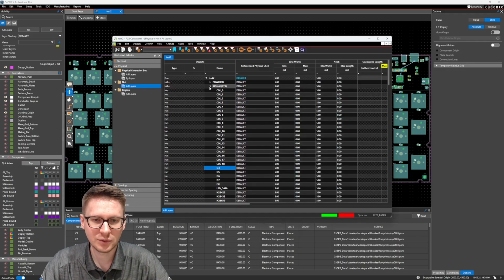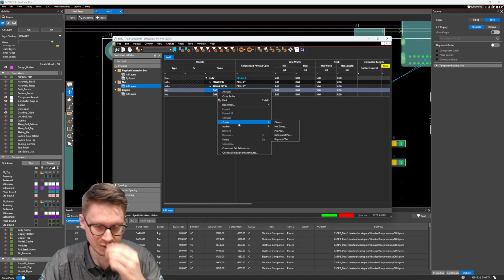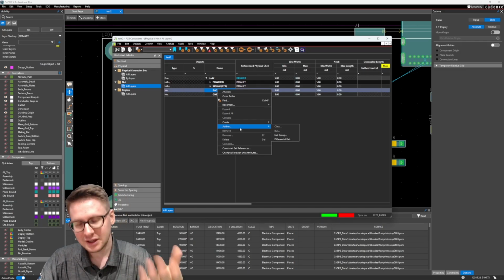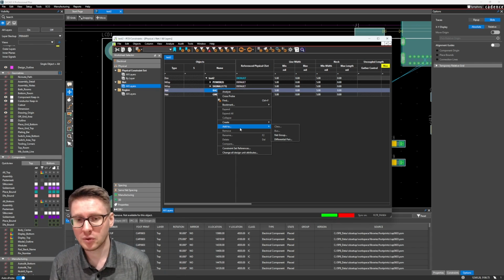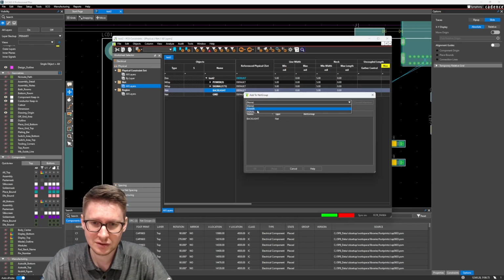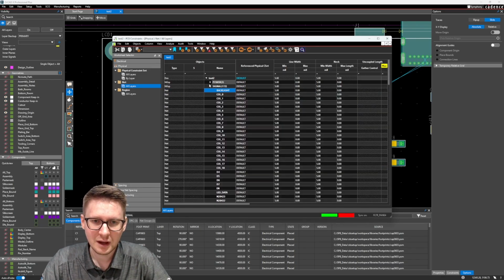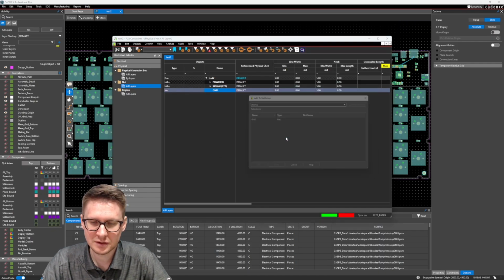And then finally, we have this backlight. I believe I wanted this to be also a signal net. Technically the backlight, if we were working with a much bigger screen, for example, you might want to have a little bit of a thicker trace. But in this case, this LCD really does not use a lot of power, so we'll add this to the signal group as well. And our ground net, this is actually a power net, so we will add this to our power net group.